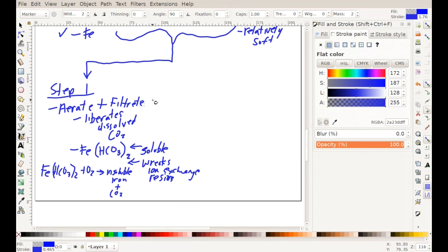And a Patterson iron filter was brilliant. What it had was a little aerator, so the well water would go through an aerator. The aerator would put a bunch of atmospheric air into the water, forming this insoluble iron form, and then there's a filter downstream of it that would filter out the iron, and that way you wouldn't wreck your softener beads.